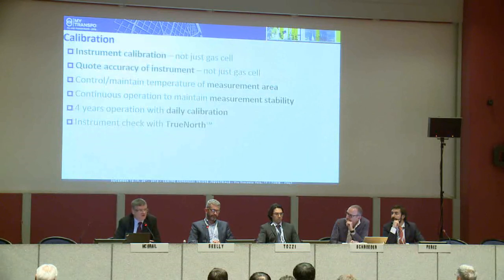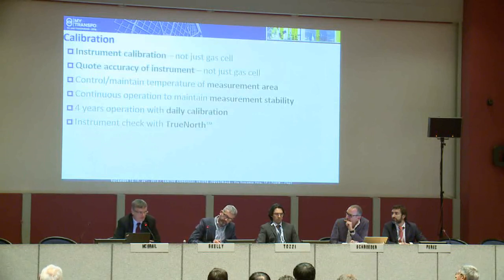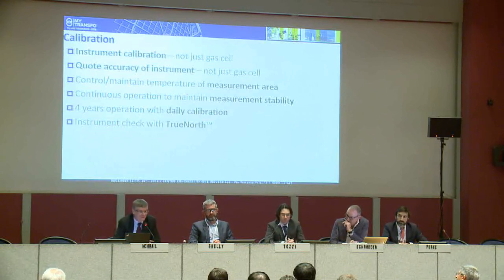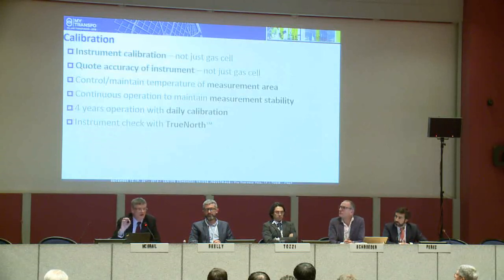Related to that, 2 other things. The carrier gas approach means you've controlled the gas which is going through the cell. The cell is going to take gas which is from the transformer, dissolved in oil, and we'll add that to the carrier gas. We'll also have moisture within the transformer. Those substances can affect the way the sensors work. If I have a sensor which is providing GC, they are part of the measurement.